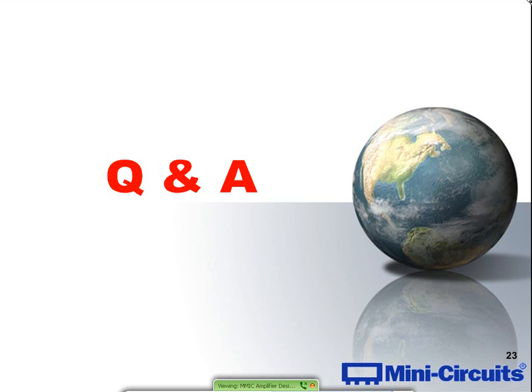Okay, when would you select PHEMT versus InGaP HBT for a specific design? It's all about the application. The InGaP HBT is really more suited for broadband, medium power solutions. The best noise figures we can get out of an InGaP HBT design are about 3.5 dB, so I wouldn't use it for a low noise application. In the case of low noise, I would go exclusively with a PHEMT approach, where we can get that extremely low noise.